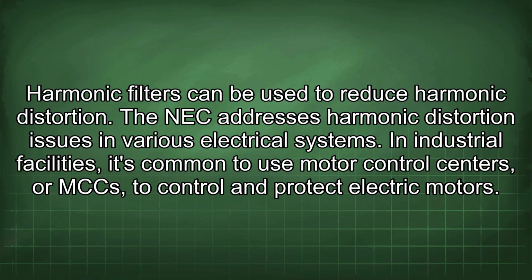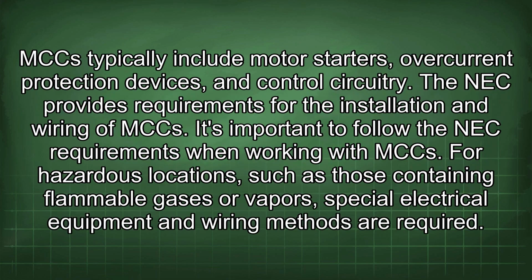In industrial facilities, it's common to use motor control centers, or MCCs, to control and protect electric motors. MCCs typically include motor starters, overcurrent protection devices, and control circuitry. The NEC provides requirements for the installation and wiring of MCCs. It's important to follow the NEC requirements when working with MCCs.